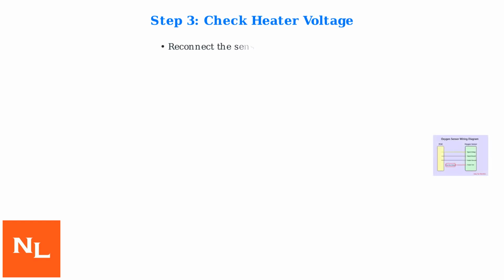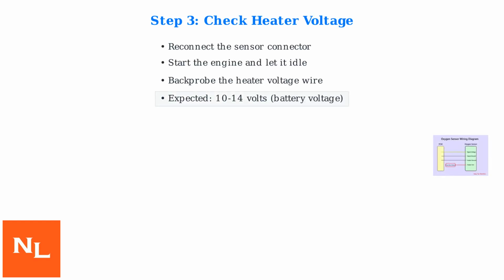Finally, check the voltage at the heater circuit while the engine is running. This ensures the PCM is properly supplying power to the heater. Low or no voltage confirms a circuit problem beyond the sensor itself.